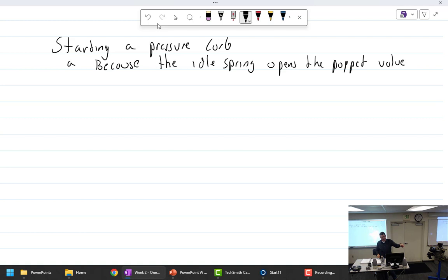It's the master switch. So if I get in an airplane and it's all off, and I put the key in and I turn it, what does it do? Nothing. It makes the mags hot. I shouldn't say turn the mags on, somebody's going to think it started turning at that point. So if you had a completely dead battery, you turn on the master switch, and nothing happens. Not a click, not a pop, nothing. You're like, uh-oh, battery's completely dead. You can turn the key on and get out, and you can pull the prop through and start it.